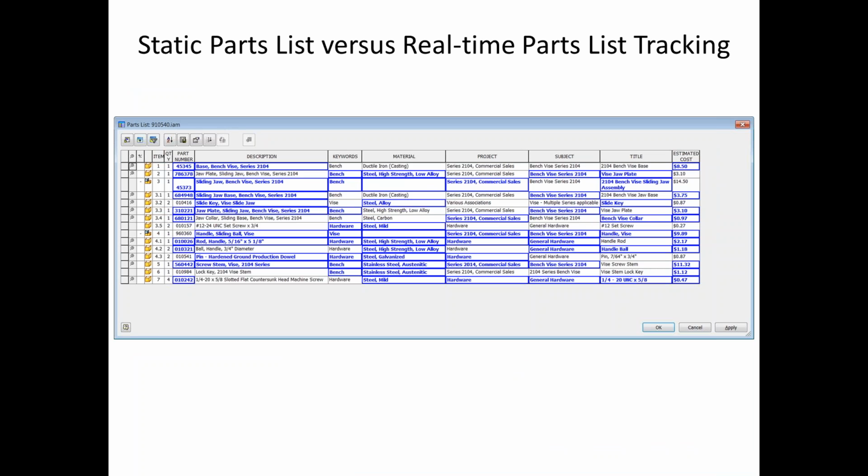When you pull up that parts list and just start making changes to the fields, they may already have information in there. In the material column, a notorious place to talk about, a lot of new parts in Inventor are assigned a generic material. There's no specific material association built to it. So you'll come in here and look at the material column and it'll just be filled up with generic, generic, generic, and people will start going in there and typing that out and changing that.